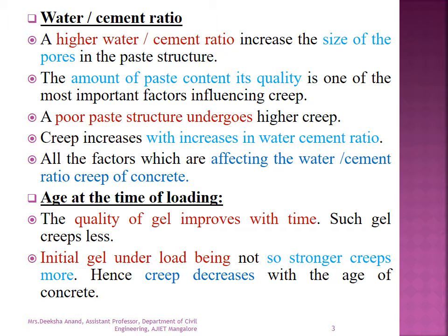So the next one is age at the time of loading. The quality of the gel improves with time. In such gel, creep is less. Initially, the gel undergoes loading when it is not so strong, so it creeps more. Hence, creep decreases with the age of the concrete.